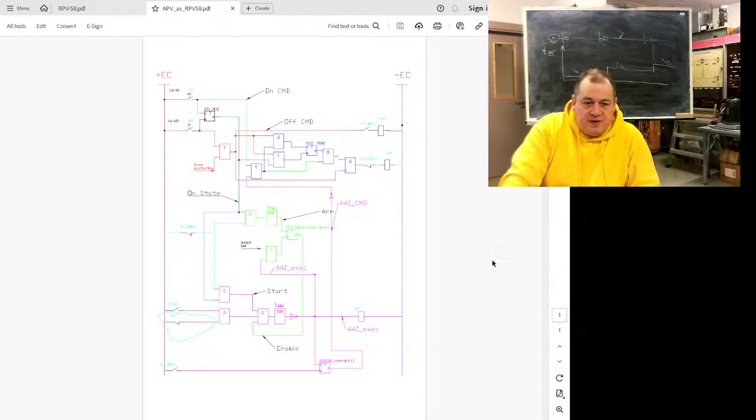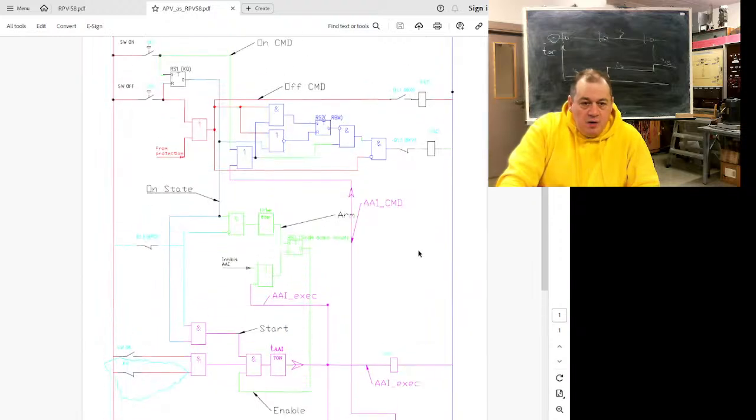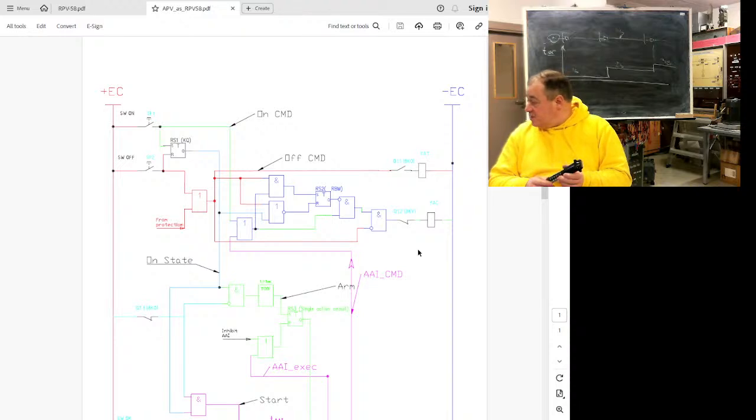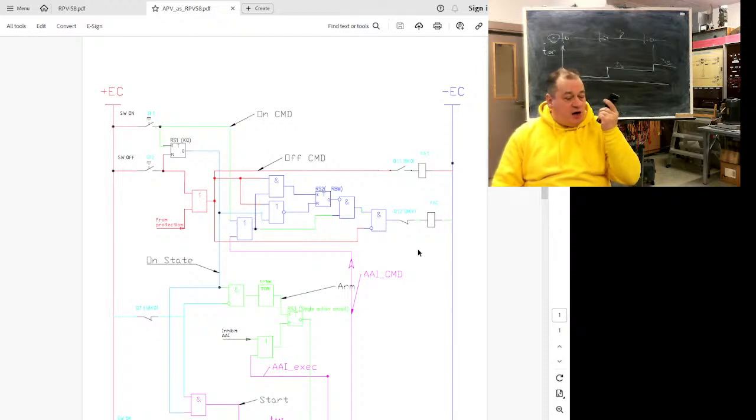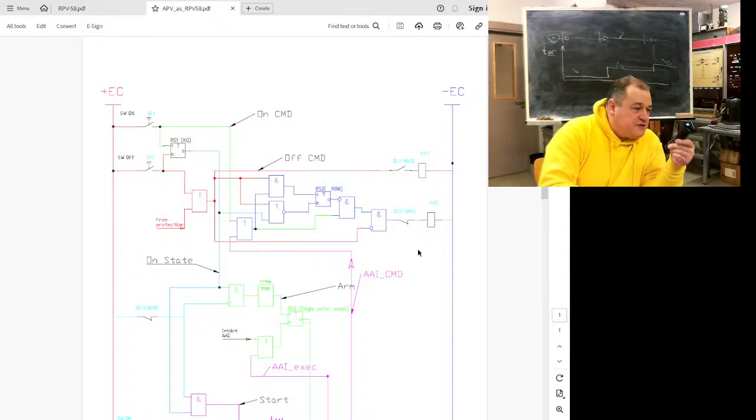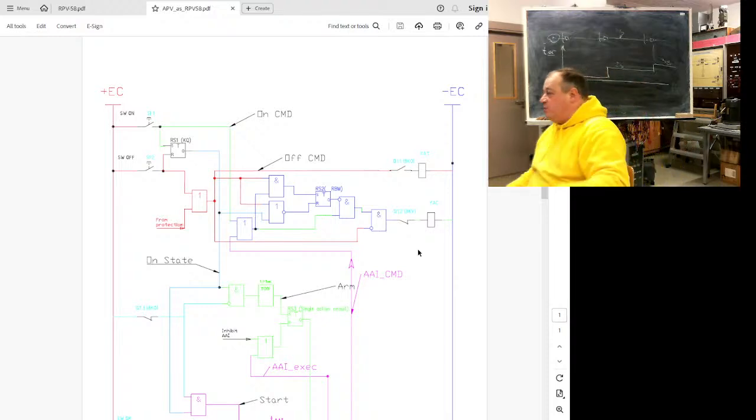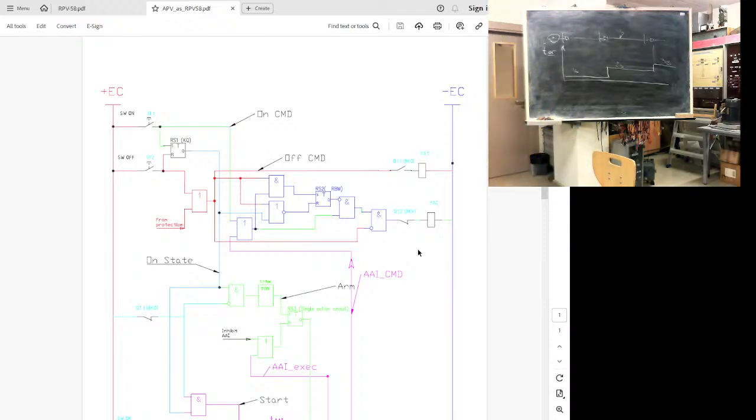Here is the modern incarnation of the same logic. One of the problems with the original P58, it requires a switch signal to reconnect the line. How to say, it emerges on what condition? The state of the control switch is compared to the state of the circuit breaker. Yeah? But if we have dispatch control or remote control, there will be no signal from the switch, from the control handle.